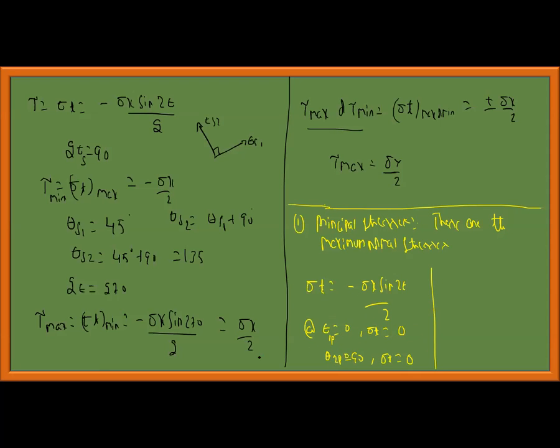But you should always remember that when I talk about shear stresses, the maximum value obtained like this for axial loading is better. But for these shear stresses, there are also normal stresses induced. Let us find. I have found out the shear stresses. Now let us go and calculate. I will indicate the shear stress planes as S1 and S2, and the principal stress planes with a P suffix, as P1 and P2.